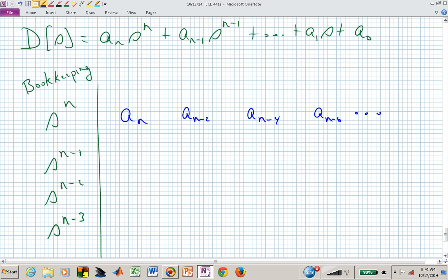You need to make sure that you jump over or don't jump over coefficients that might be 0. If you start with a 4th order polynomial, you have a sub 4, then you have a sub 2, then you have a sub 0, and that top row is done. Now the second row in the Routh array picks up the other coefficients in that polynomial.